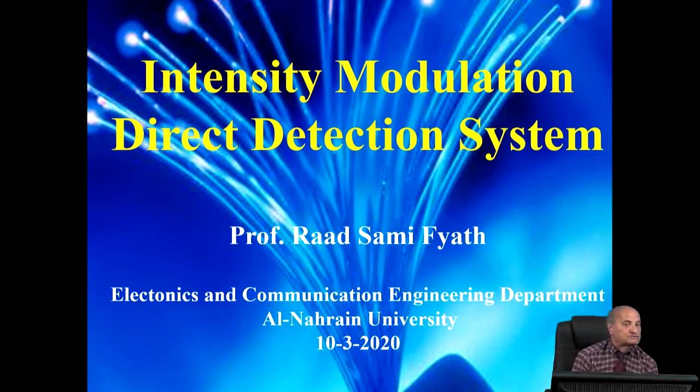The other one, which is more expensive, is the coherent or synchronous detection. In optical communication, the receiver must use a local laser operating synchronously with that used in the transmitter. Coherent detection, which is the subject of the next lecture, is more expensive, but it gives more performance compared with direct detection.